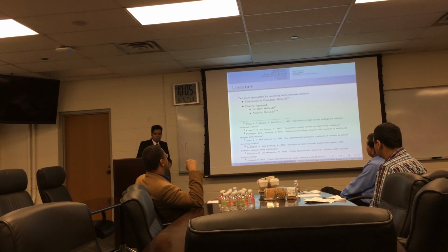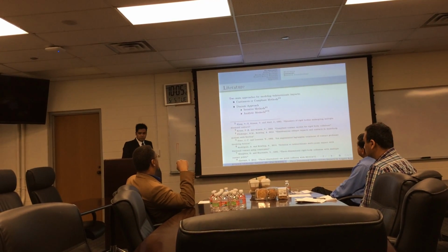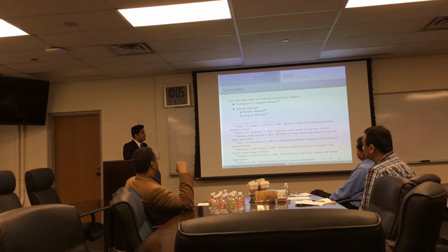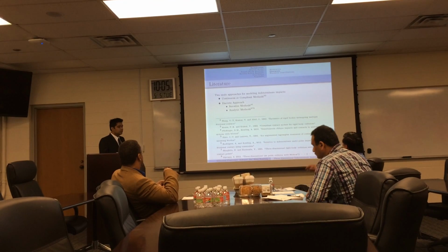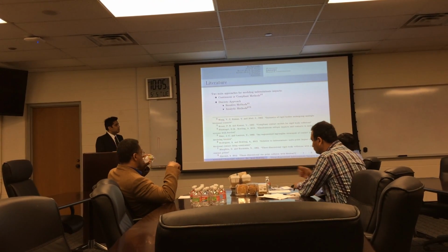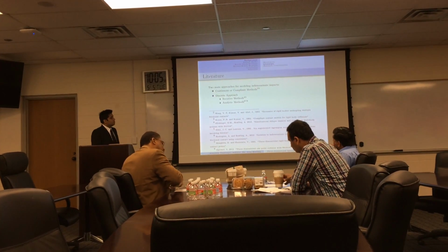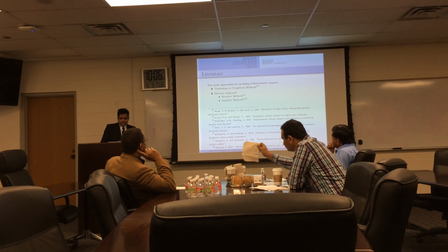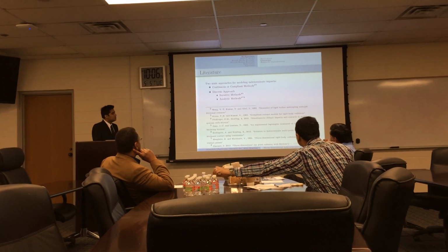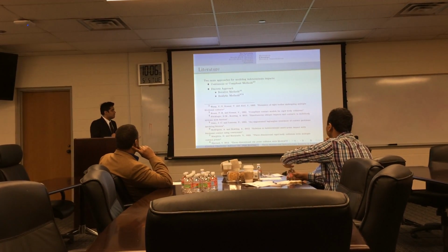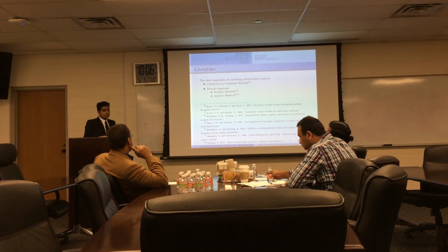So in the literature, there are 2 main approaches for addressing indeterminate impact problems. One is the continuous or the complying method. In this, essentially the indeterminacy is solved by adding degrees of freedom, and this is done by making the impacting bodies deformable, so that it no longer remains indeterminate. And the other approach is the discrete approach. In the discrete approach, the idea is to stop the simulation whenever a contact is detected, and then restart with some sort of post-impact velocities as the initial conditions.